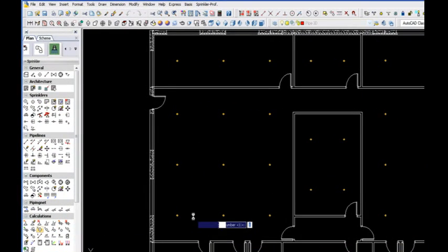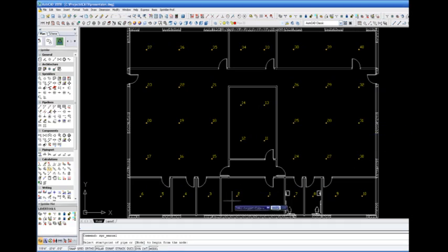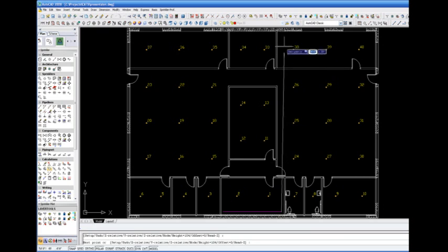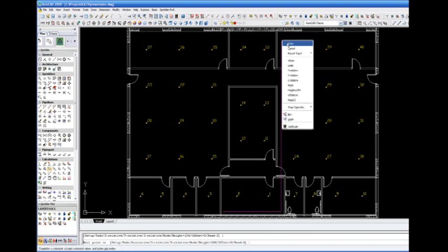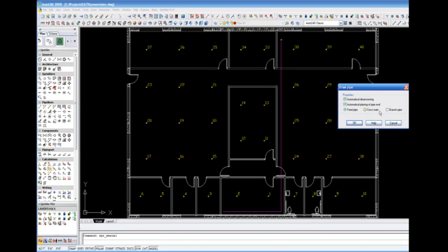In the C.A.T.S Commander under Pipelines, you find Draw Pipes. This is similar to the AutoCAD function line. Begin by starting at the floor and giving the line an elevation in Z direction. Then move the line in X direction. Finally, move the line in the Y direction. You have now established the center line of a fire sprinkler main.